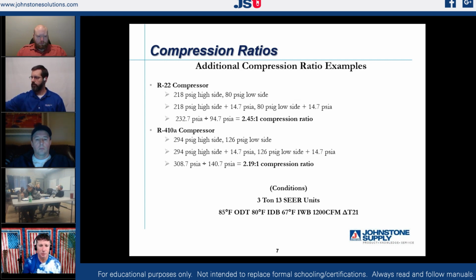Let's use this same principle. So that was a low temperature, low pressure R134A system. Let's look at it in our world, and let's look at what our compressors are actually doing. So on this system, we're going to look at an R22 system, right? This is a comparable operating 3-ton 13 SEER unit.